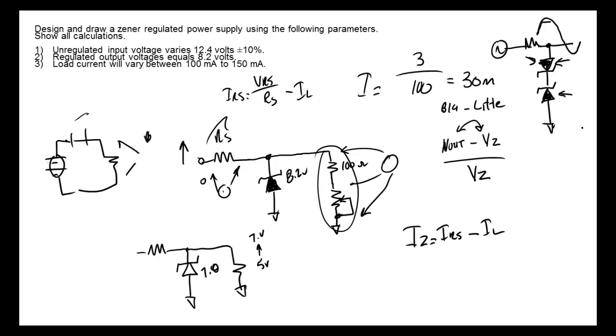But we've got to add another component to that. They're also used in crowbar circuits, where if the output tries to go up above a certain limit, it just cuts it off. So crowbar circuits are different. So we use Zeners all over the place, besides for just what? Power supplies. Anytime we want to limit a voltage to a certain thing, then we'll do it that way.